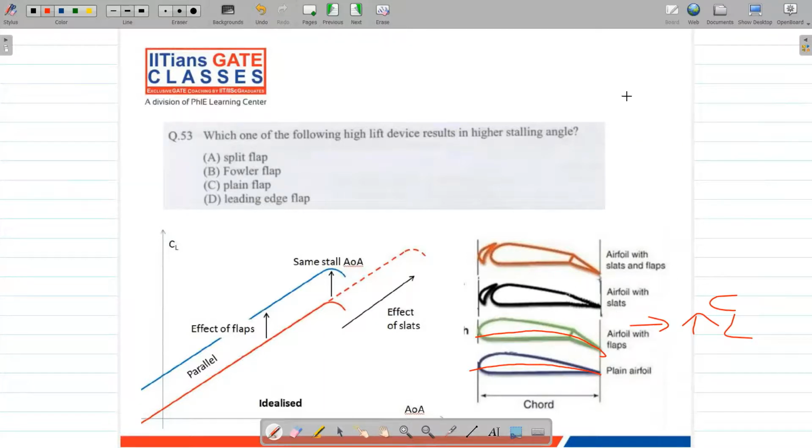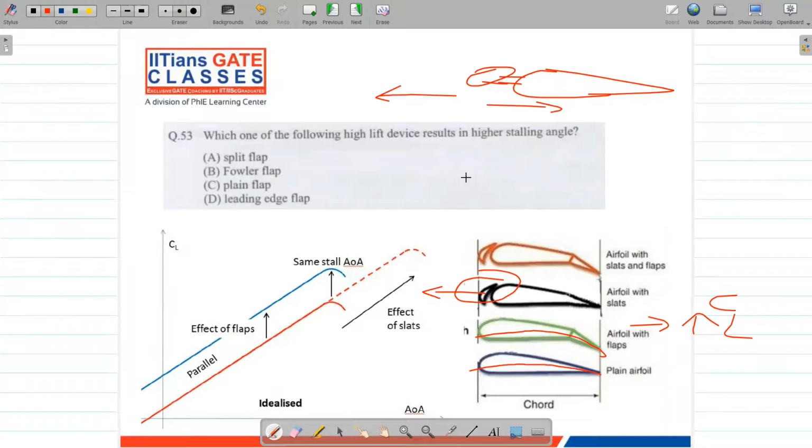And there are also some flaps which do something like what a slat does. So a slat is like an attachment on the leading edge of your airfoil. This attachment can be pulled away as well as towards your airfoil. Let's say initially my slat is somewhat like this, somewhere here, and then joined to my airfoil with some rod. I can always pull this guy front and back, and I could have a configuration something like this. I pulled it so much to the front that it's something like this. I'm just exaggerating, but this is how slats work.